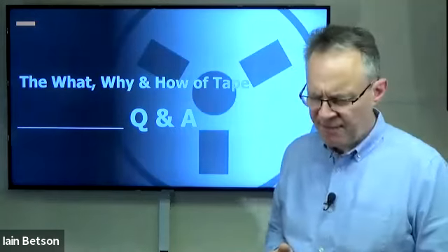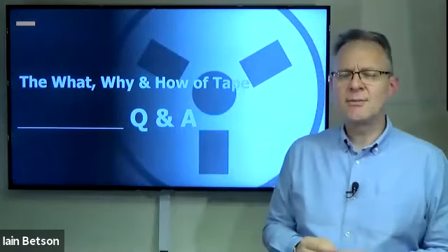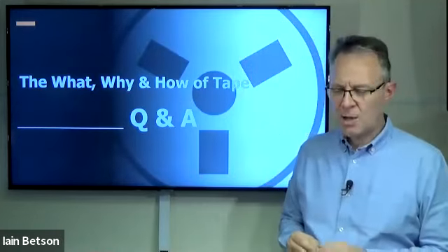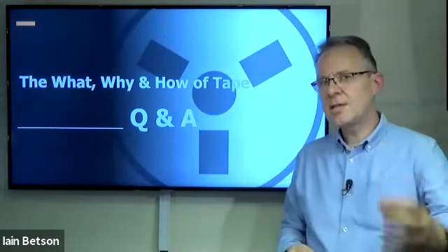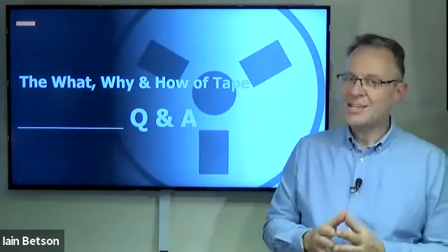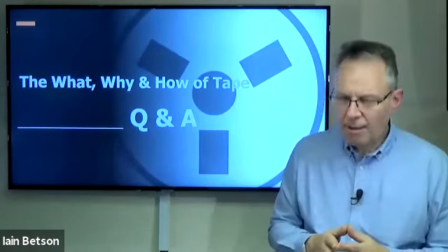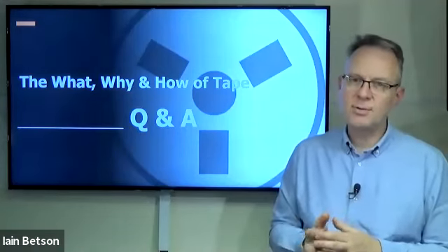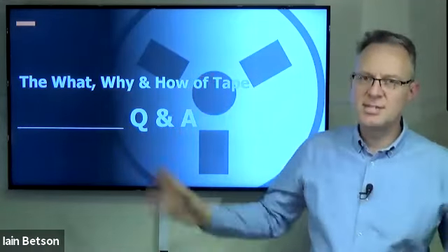If you've seen the film Bohemian Rhapsody, I think when that was being launched, they had Brian May and Roger Taylor of the band Queen saying that when they recorded Bohemian Rhapsody, they did so many overdubs, so many retakes on the 2-inch tape, that you could see daylight through it. Well, I actually have to take issue with that, because if you could see daylight through that tape, you haven't got any oxide on it, and Bohemian Rhapsody would have just disappeared, and they'd have had to re-record it on fresh tape. But of course they did a lot of passes on that tape, and as I said, every time you run it through the machine, oxide will come off.